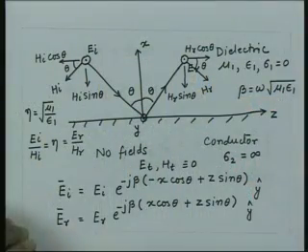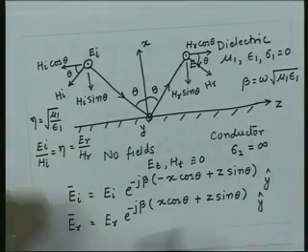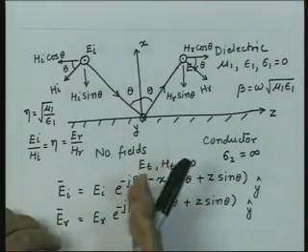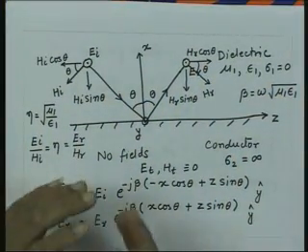What that means is that if you have a conducting boundary, then the boundary can be used to guide the energy along with it. So a conducting boundary has a capability of guiding the electromagnetic energy. So you launch a wave at any arbitrary angle, and what you will find is that the net power flow is always along the surface of this interface. Essentially this is the thing which is used in creating what is called a waveguide. So in a waveguiding structure we use the conducting boundaries so that the electromagnetic energy is guided along these boundaries.